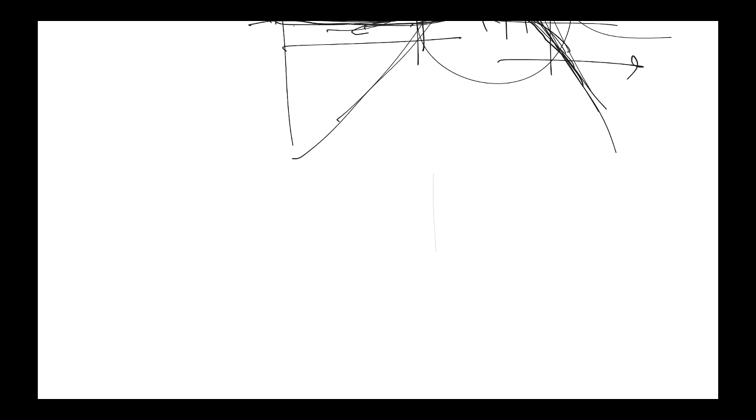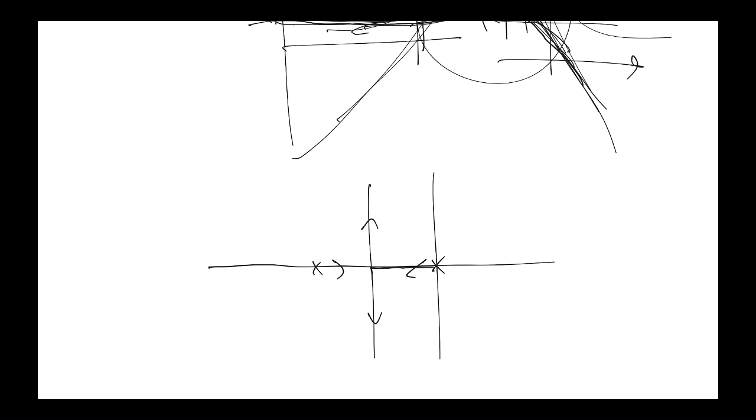Right, and it's the same as thinking on root locus plots. If we have a system like this and increase the gain, these come together and this one's getting faster. But when it splits apart, it stops getting faster, and you just get more oscillations, right?